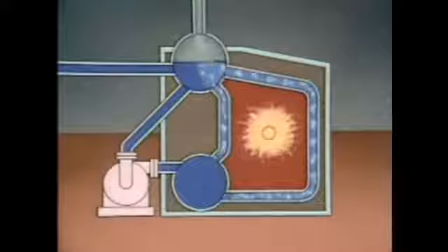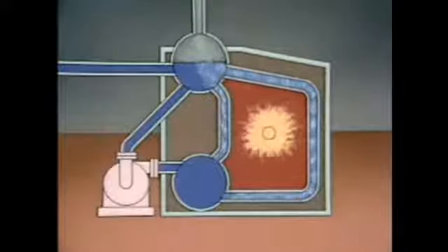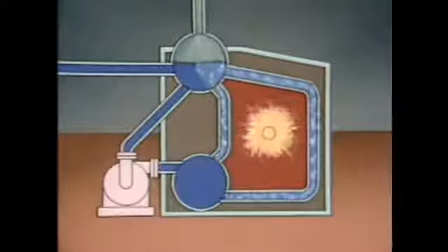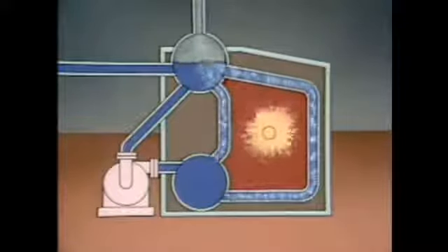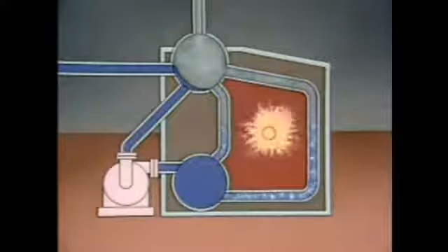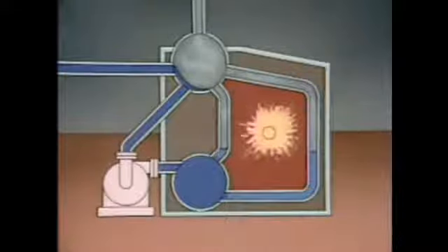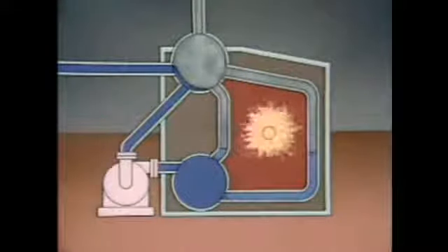If the pump circulates the water through the drums and the tubes, the boiler will operate as it's supposed to. Hypothetically, though, if the pump stops, the water will no longer circulate properly, and the boiler could boil dry and become damaged. To make sure there's proper water flow, most controlled circulation boilers use 2 or more pumps. So, even if one pump stops, the other pump will provide enough circulation to prevent damage to the tubes.